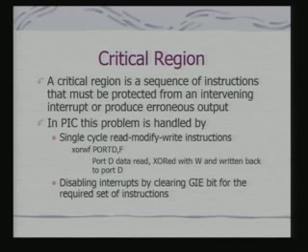So, read, modify, write instructions help you to implement critical regions, particularly with reference to your external world and external inputs. The other thing is obvious: if I disable my GIE bit over a range of code, I shall ensure a critical region. But at the same time, in this case I am increasing the interrupt delay. So, that constraint I have to keep in mind. Also, I have told you that we can use a swap instruction to implement this kind of synchronizing primitive to ensure correctness of critical regions.